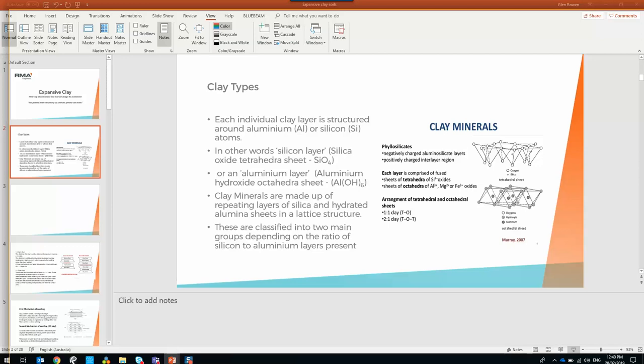So the advantages are, it's the best option because everything's out of the ground. The clay, where it's expanding and contracting, all your surfaces are fully suspended in the air, and you've just got one dropper into the ground, so you avoid breakages and that sort of thing. So the disadvantages, especially in the commercial world, is it's above the ground, and you've got to have ramps up to it and deal with those sort of things.